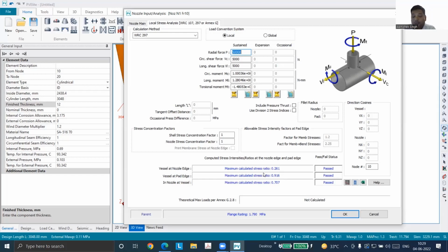You might have seen that gussets are only for smaller size nozzles, normally for 2-inch or very rarely for 3-inch. Mainly for 2-inch, you'll see gussets, or we call them stiffeners, attached to that nozzle. What do you think may be the reason for that? The nozzle section is very small to withstand the bending. It's a cantilever condition, no?